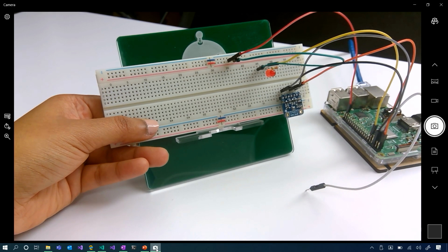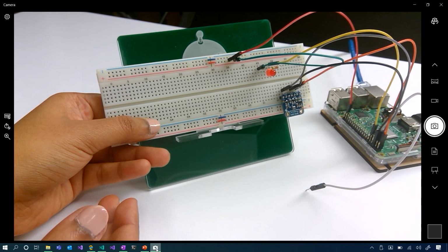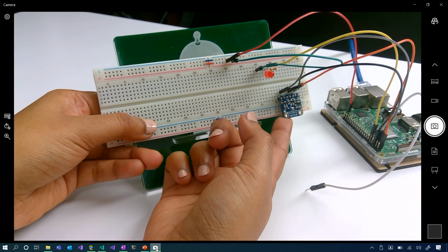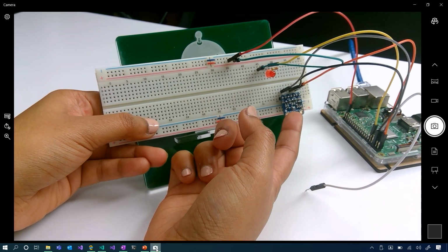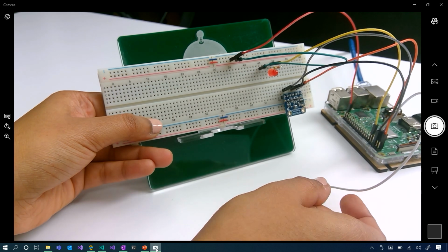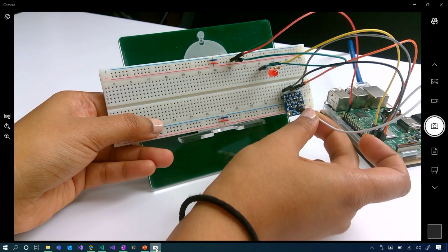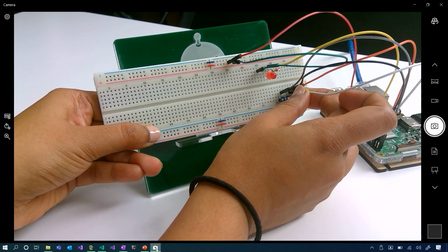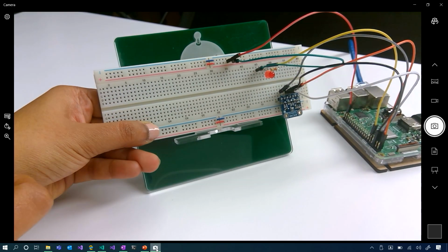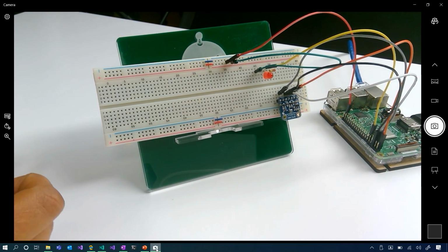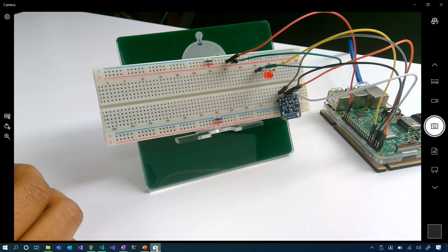So following the Fritzing diagram, I have my breadboard set up here. I've connected the BME 280 sensor to the breadboard. I have made the 3 connections of the wires onto the Raspberry Pi already. And this is the last and 4th connection that I have to make to the SCK port. With this complete, this finishes our circuit that we will use for the BME 280 pressure sensor.